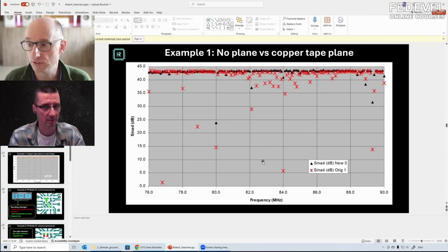because there's no ground. So there's no reference. There's no 0 point anywhere in the circuit. So basically everything is moving with respect to everything else all the time on the board. And that simply gets into your RF input and ruins your audio performance. So here you see a whole lot of things happening at the same time. You see harmonics, you see lack of grounding, and therefore interference.